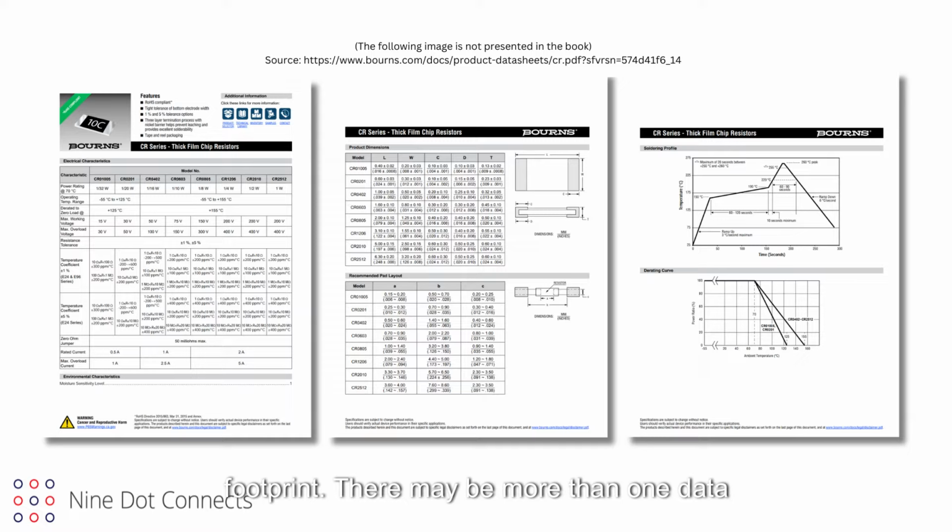There may be more than one datasheet, depending on the complexity of the component and the component manufacturer's way of handling their documentation. In some cases, the datasheet is more like a data book, with several hundred pages. All datasheets associated to a particular component should be added to the symbol as links or references. This will allow the individuals testing and/or debugging the circuit to quickly obtain the datasheets as needed.